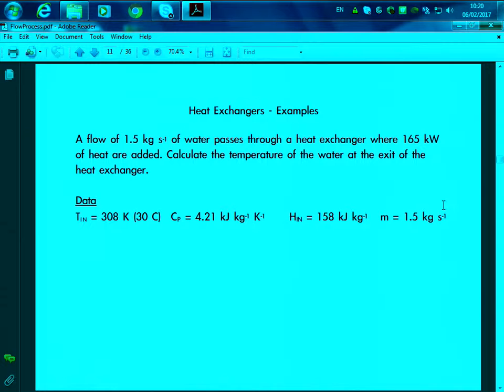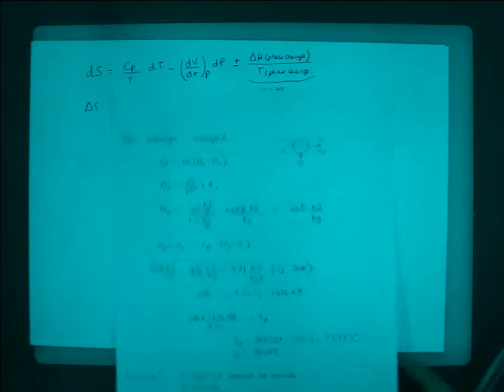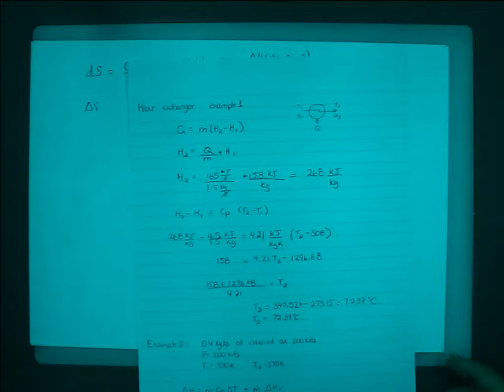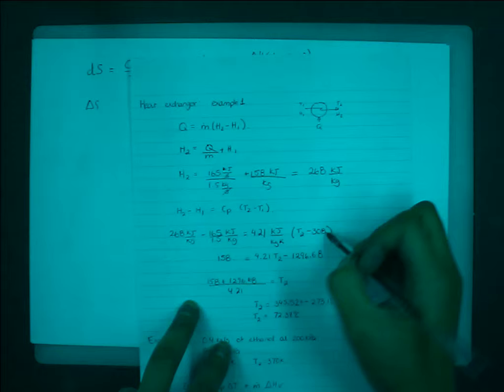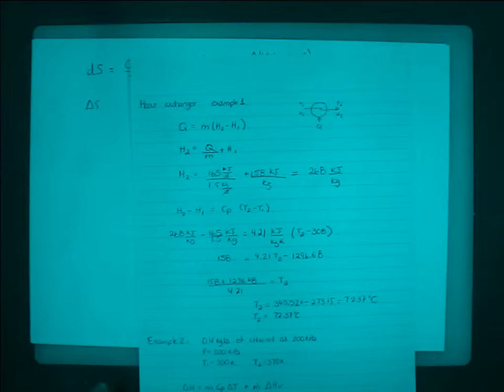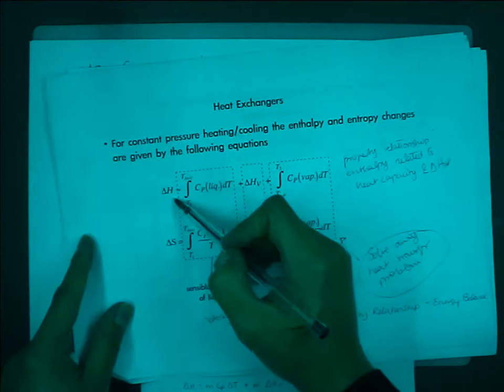Here, basically, the first thing that we are going to assume, having this change in enthalpy, is that the liquid doesn't vaporize. Okay? So you always start like that. If it doesn't vaporize, then the only thing that you're using is this part of the chart. And then Cp delta T, we also saw, is basically delta H, and delta H times the mass will be the heat that you need in the heat exchanger, right? We saw that at the beginning of the lecture.